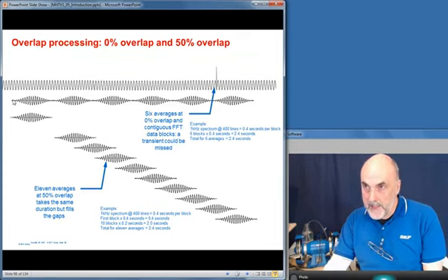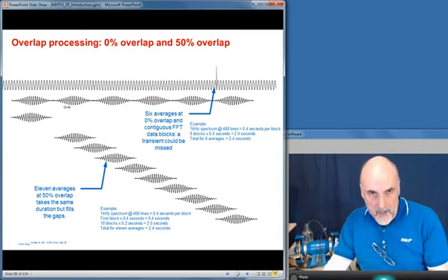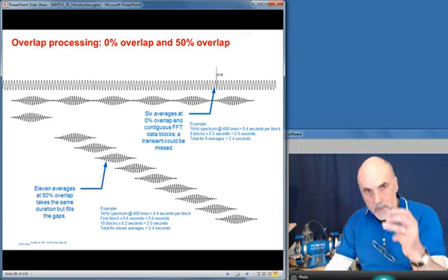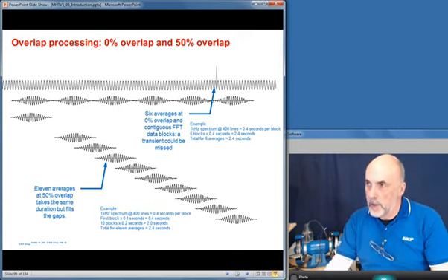In normal circumstances, if you're doing, say, 6 averages, you would take your Hanning weighted data, do the FFT, store it, do another one, add it to the memory and divide by 2, and do that 6 times. You've got the average of 6 measurements. This works for a continuous signal, but starts to fall down and give you problems if you're dealing with transients, because that transient could well fall in between 2 of your Hanning weighted windows.